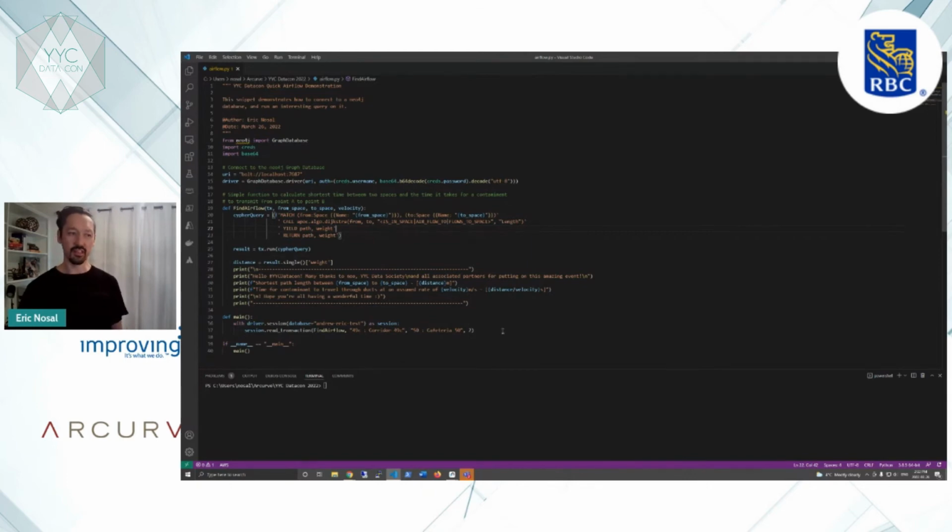Other assumptions are that the airflow through the ductwork is laminar. Again, this serves to simplify the velocity calculations, and that the system's in some sort of steady state with the airflow circulating as it normally does. So with this little program, which I made longer than it had to be, because I wanted to make it fun, we can just run it here.